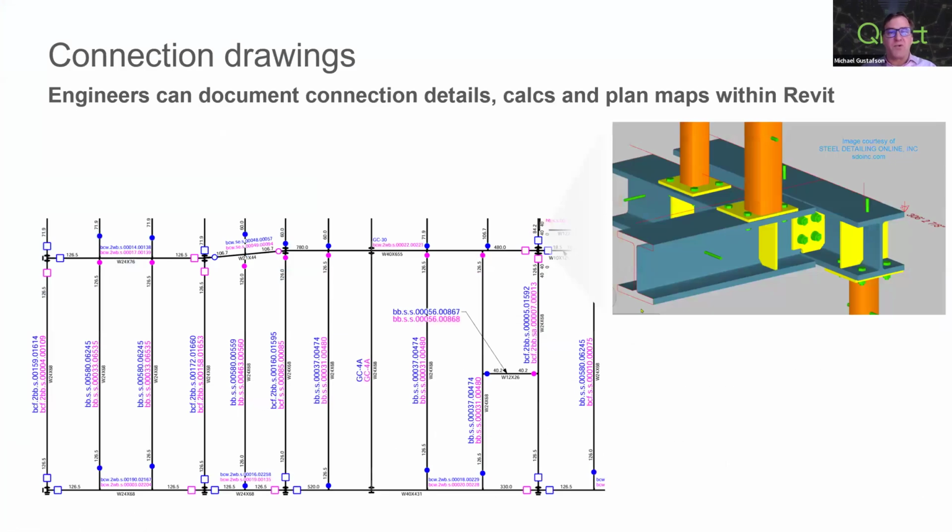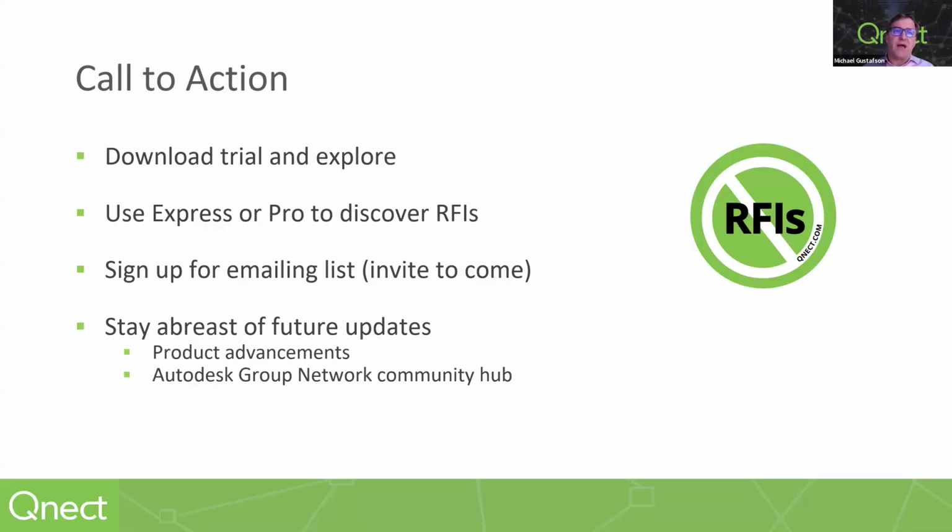Here's just a visual example of what we do in Tekla today, and we could do in Revit as well. Connection codes, flagging doublers and stiffeners, even having 3D visualization of connections. Really excited about that direction we're going and the feedback we've gotten.